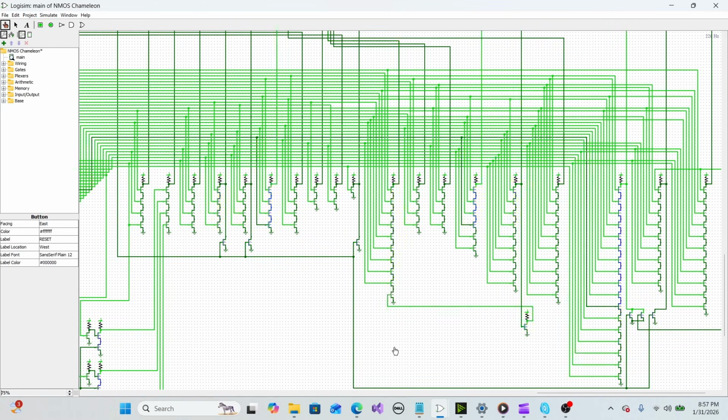If some of these incorrect values accidentally cause an asynchronous register's input enable signal to go high, then garbage data might be loaded into that register, which would corrupt the entire execution sequence. Disabling the input enable signals for such registers while the clock is high is a simple but effective method to eliminate that possibility. I already did this anyway in the original logic diagram for the RAM's read and write signals, since the RAM is also asynchronous. So it was a fairly straightforward thing to add more such logic here to protect the new asynchronous registers.